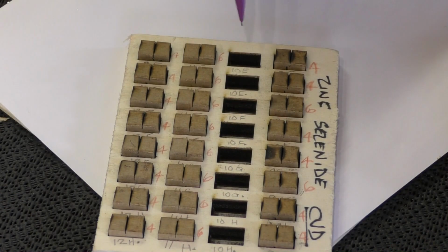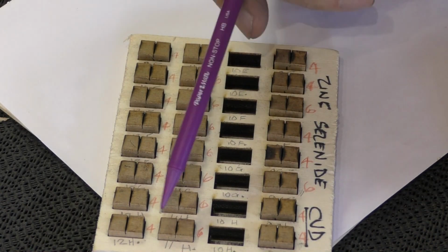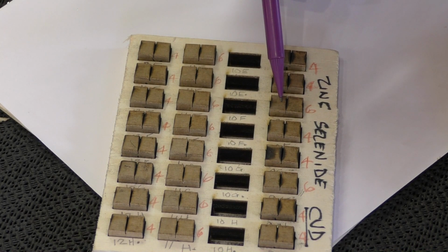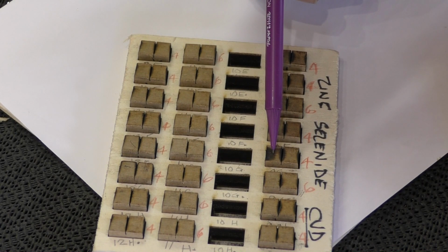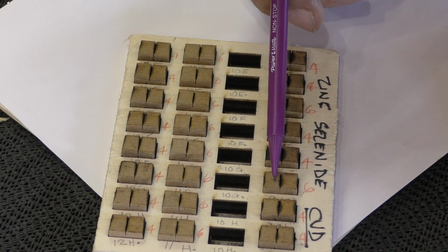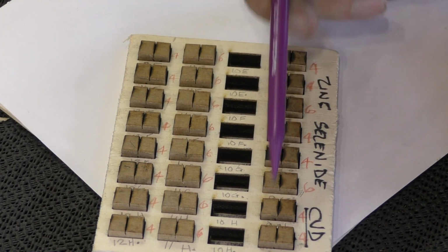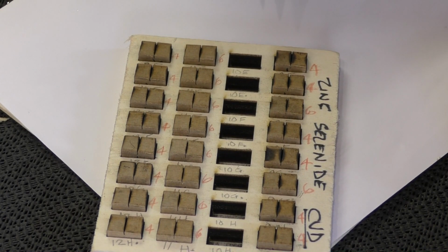So wherever you look on this set of results for MDF, and I've chosen MDF because the black lines are much easier to see. This being a plano convex 1.5 inch lens, flat side down. Here it is dropped 3mm into the material. Then it's flat side up, dropped 3mm into the material. Then we've got a meniscus lens, flat side down, dropped 3mm into the material, flat side up, dropped 3mm into the material. Now, wherever you look down those 1.5 inch lenses, regardless of orientation or shape, you produce parallel holes.